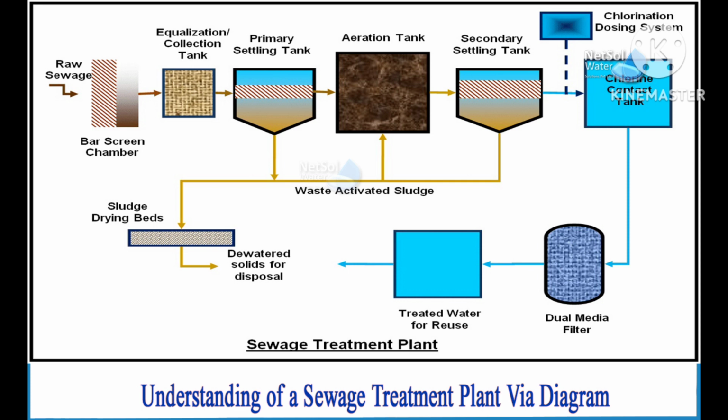Stage number 5 is secondary clarifier. Pumping treated wastewater through a secondary clarifier enables any lingering organic matter to spread out of the flow of treated water. The sixth stage is chlorination or disinfection. This is to eliminate any leftover bacteria in the contact chamber.